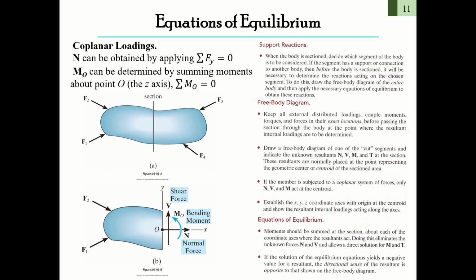This is a three-dimensional problem. But if you use the x direction, y direction, and the out-of-plane direction is the z direction, and if you put F1, F2, F3, F4 in the xy plane, there is no other force along the z direction, that is called the coplanar load.